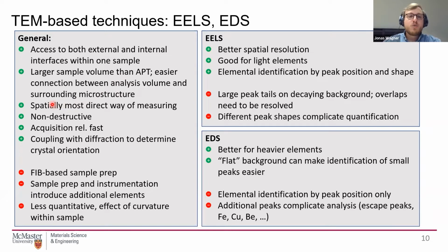In Atom Probe, we are reconstructing a data set that is based on its evaporation or field evaporation characteristics. In Auger, we extract our spatial information from the interaction of an ion beam with the matter. So all those are secondary ways to get the spatial information, while in TEM, we just have our beam that scans over the sample. And here, if our instrument allows for atomic resolution, then it is more on the sample side to limit how sharp we see the interface in TEM.